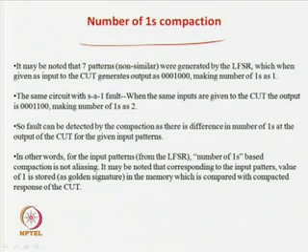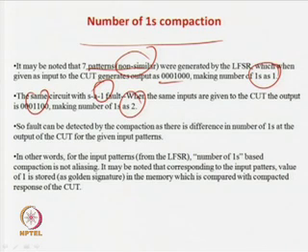So, in the last case we see that 7 non-similar patterns, I mean there is no repetition of patterns, were applied to the LFSR, and the circuit generated this one. So, the number of ones is 1. So, this is a compression. The same circuit when there is a stuck-at fault has 2 ones. So, the number of ones is 2. As there is a difference in the number of ones, the fault is detected.